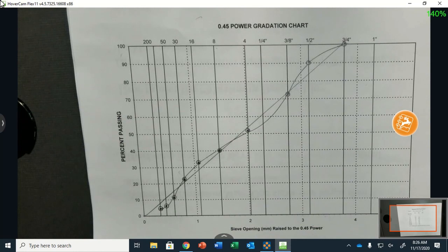That's in theory. So if all our data points are in there, we don't have hardly any air voids in the space between the aggregates. Okay? But in asphalt, we do not want that. Because remember, just like concrete, we want the cement paste to completely coat the aggregate. We also want the asphalt cement or binder to completely coat the aggregate. So if our gradation is too tight, they call it too tight, we cannot accomplish that, can we? So we need to have a little bit of air voids in there.